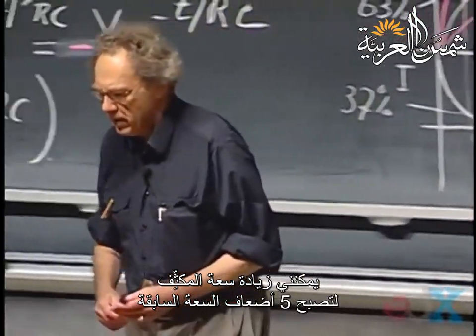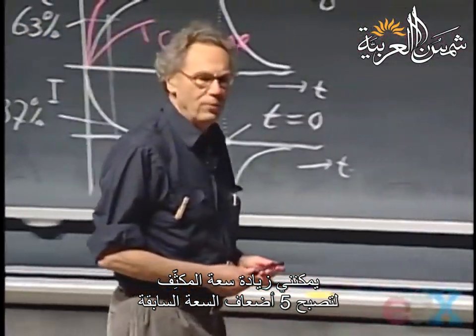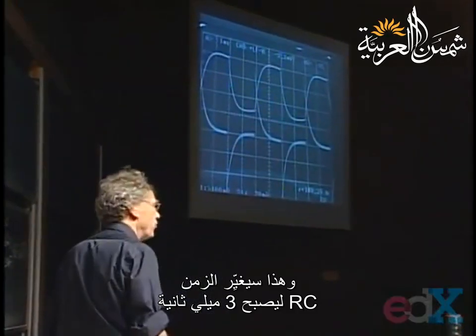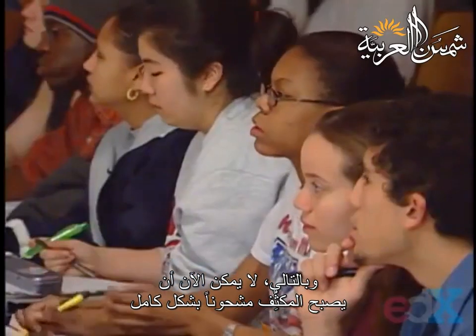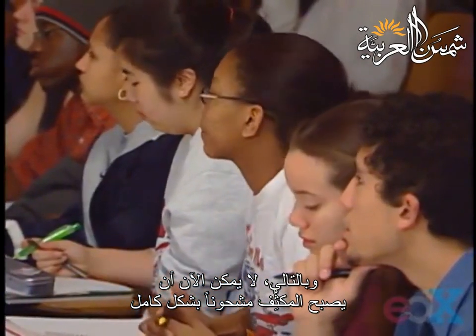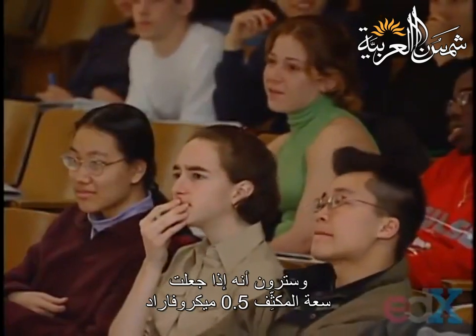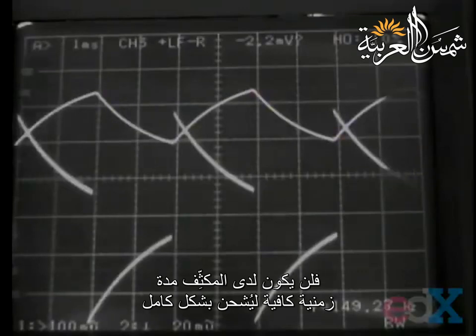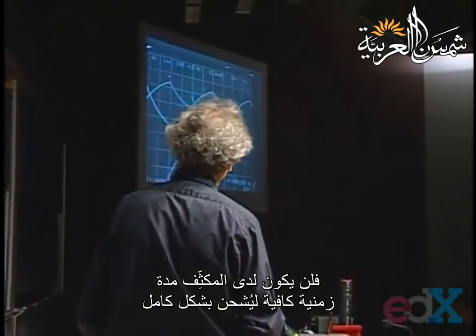What I can do now is to increase my capacitance by, for instance, a factor of 5. So that would change my RC time to 3 milliseconds. So now there is no way that the capacitor can become fully charged in the 4 milliseconds that it has. And you will see that indeed, if I make this 0.5 microfarad, then the capacitor has not enough time to get fully charged.